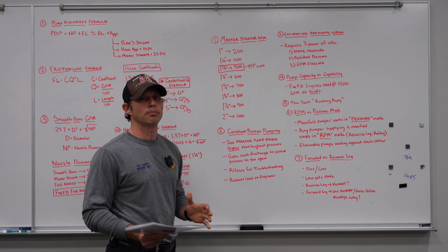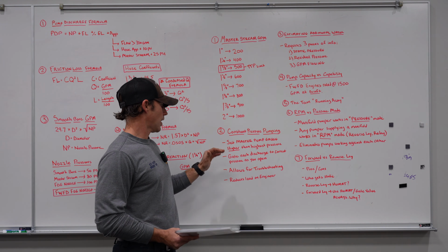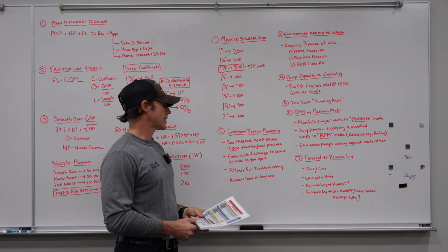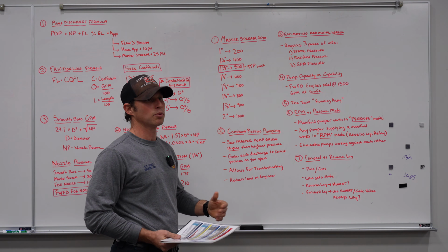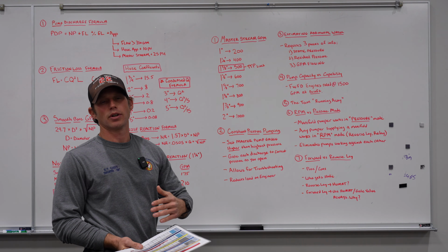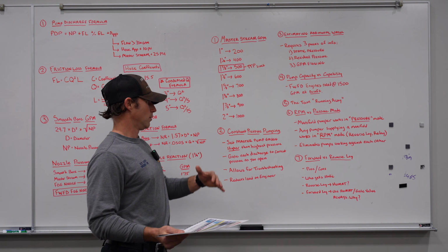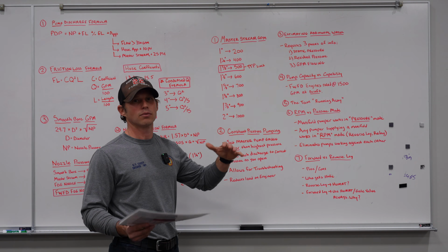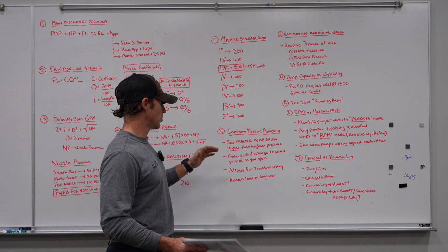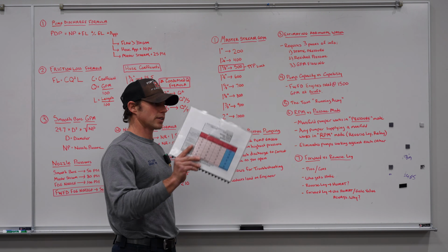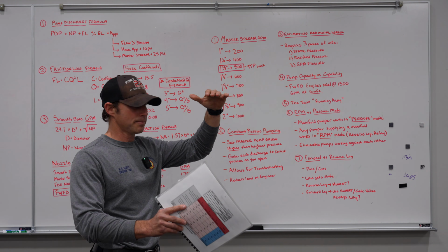Essentially, all constant pressure pumping is, you're going to pull on seam, and you're going to have a specific pressure that's higher than the highest pressure that you set your preset to. For example, if you're running old hose and your 2-inch is 150 PSI, then 160, 165, somewhere around there is a great starting point to have your preset set at. And the reason you want to do that is you pull on seam, you can set your preset higher than the highest pressure of your highest pressure line.